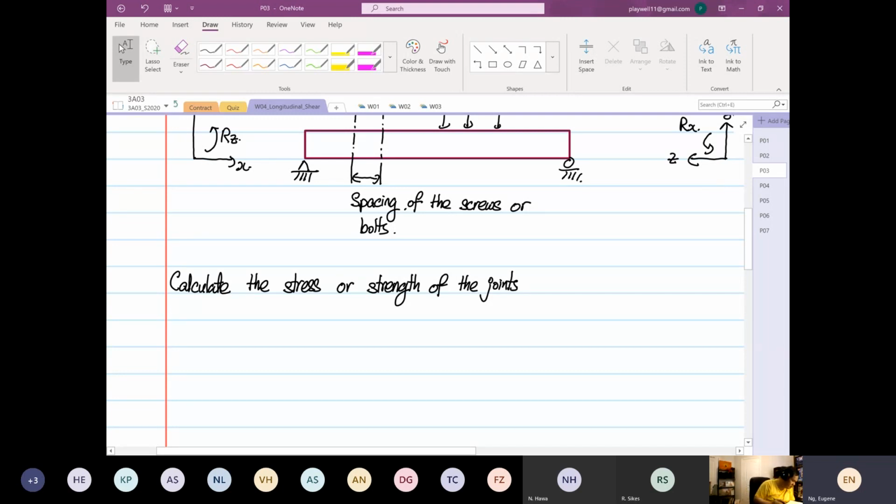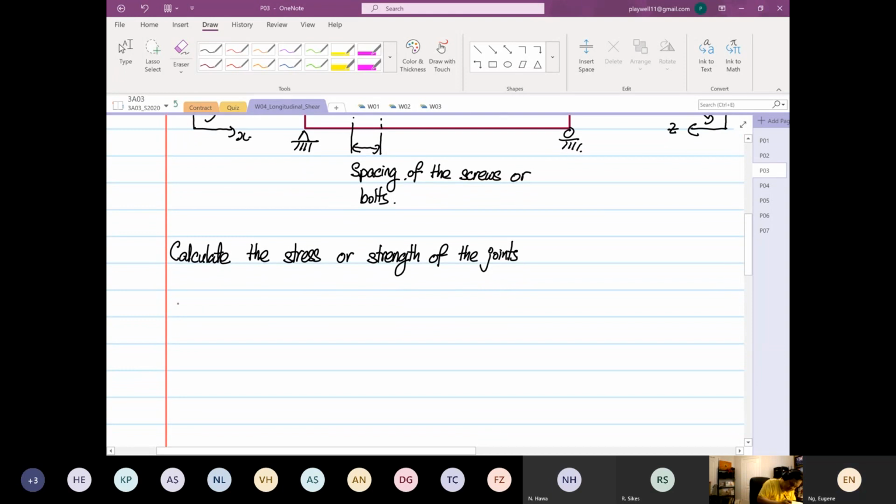Okay. So the shear flow, the key formula is the shear flow q is equal to VQ over I. So this is the formula that we should be using. And if we look at the units for the shear flow, this is Newton meter cubed divided by meter to the fourth. So the unit, if you cancel things out, is Newton per meter. Okay, so that's the formula we're going to use.